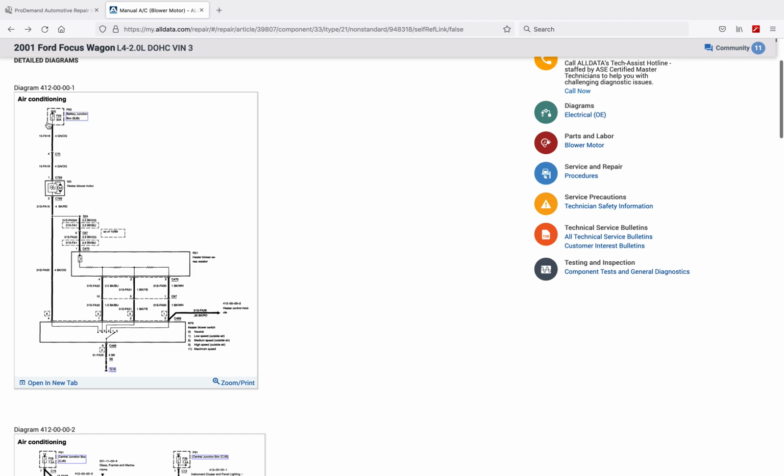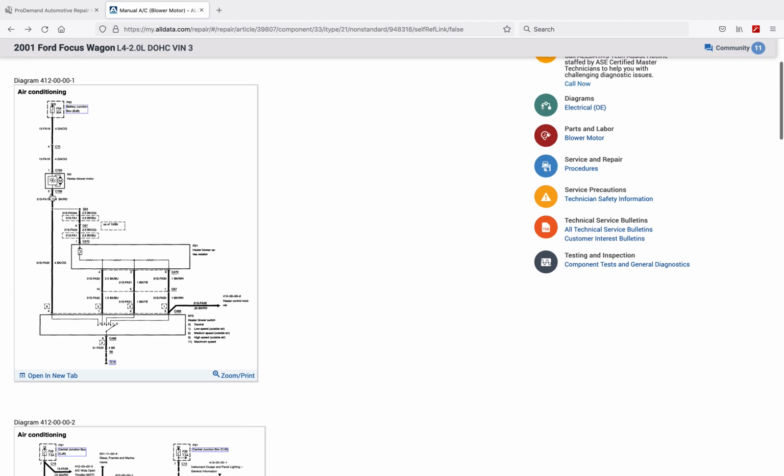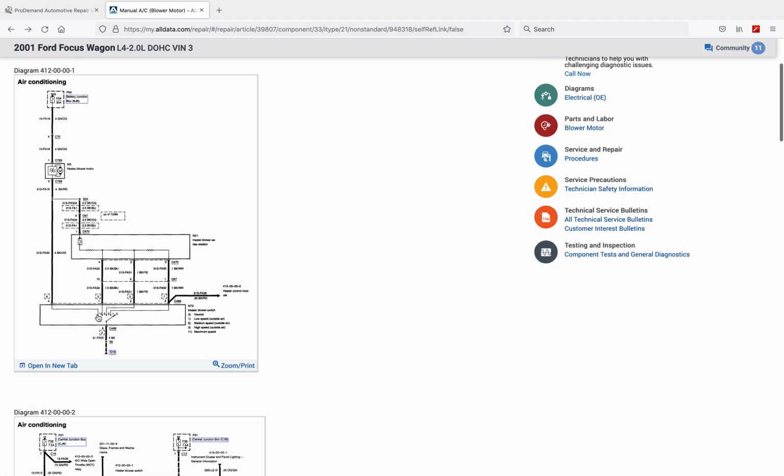So now I go from the power supply using this diagram to the blower motor, from the blower motor through the blower motor resistor through only one resistive value in the resistor to ground. So now I have one load here that's engineered in the circuit. That's the perceivable load. We see it operating. We feel the air moving. And one load here to ground.